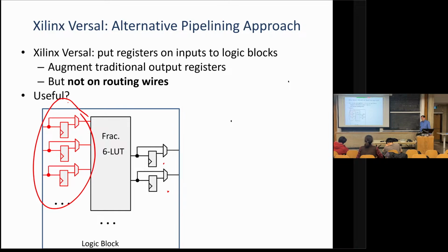You can. Okay, so they've increased the depth of pipelining. Now the thing is that this is actually kind of unbalanced though. Like the delay of a LUT's not that big. Let's say, I don't actually know exactly what it is in Versal, but 250 picoseconds would be a typical number a couple of process generations earlier. Well, say in Versal, I bet you the LUT delay is like 150 picoseconds or so.